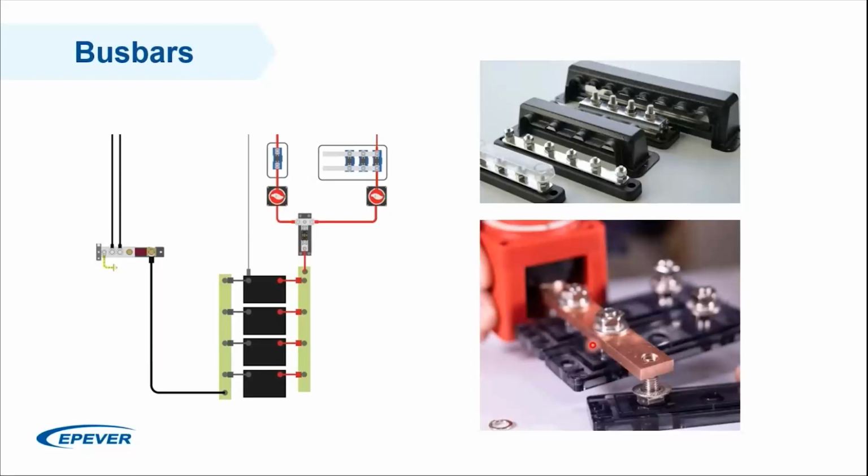And of course, it's recommended to shield the copper bars, especially if the busbar is in an open area and there is a danger that someone touches it, or something falls and provides a short circuit between the positive and the negative terminal. So it's always recommended that you cover the busbars, or you put a thermal shrink over the copper so that nothing will touch the copper itself, and there isn't any danger for short circuits.